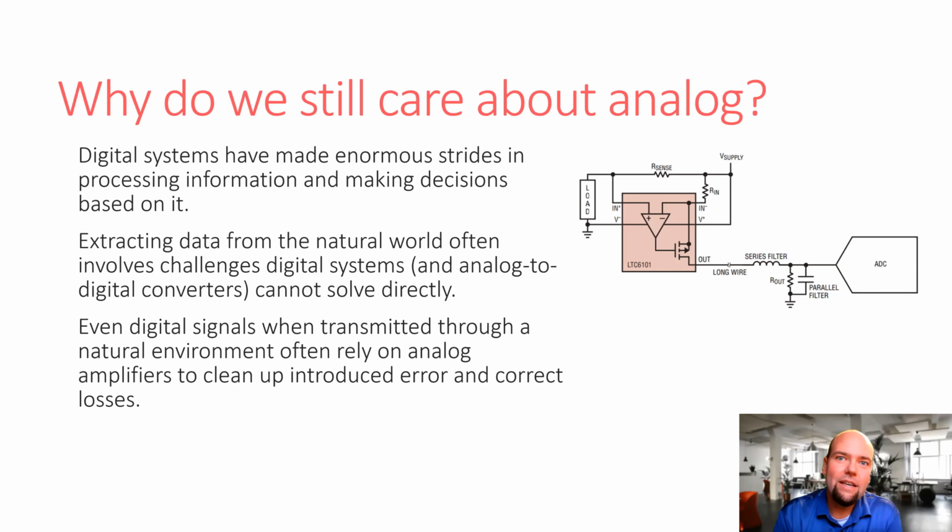The problem is this voltage signal is a very, very, very high impedance signal. This is like a 10 megaohm impedance voltage signal, right? You kind of expect that. Otherwise, you could just use a tree as a battery and plug your iPhone into a tree and charge it. So it's clearly not a low impedance voltage supply. It's a very high impedance voltage supply. And if you took a normal digital system and connected the input of the analog to digital converter right up to a tree, you'd get about nothing. Why?